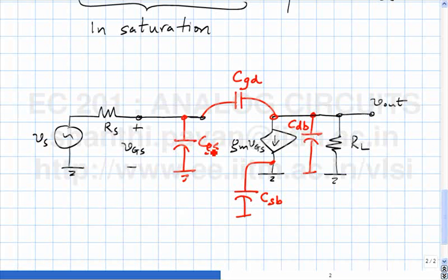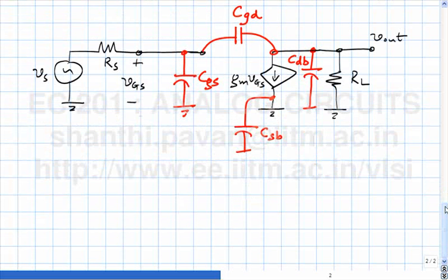Everything in black corresponds to the circuit we had at DC. The extra elements are the ones in red. So obviously, when you try and solve this linear network with memory, you will get linear differential equations. To simplify analysis, you can get into the transform domain, and now we can talk about a small signal transfer function between the output and input, just like what you do with linear networks.